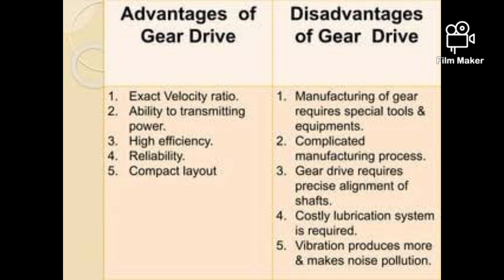And the disadvantages of gear drive: the manufacture of gears requires special tools or equipment. The error in cutting teeth may cause vibration and noise during operation. Gear drive requires precise alignment of shafts. A costly lubrication system is required. Vibration produces more noise pollution.